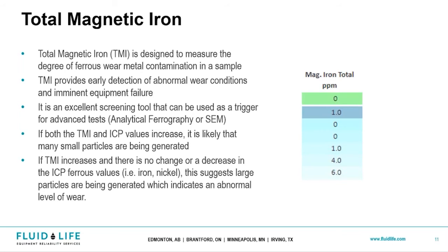And then the other thing that it does is it's going to differentiate things like alloys, whereas an ICP is only going to pick out single elements, right? So you have to do a little bit of consideration and evaluation to be like, oh yeah, there's zinc and there's copper, so I'm looking at brass. This will say, hey, this is brass, right? So it's a little bit more unique, and then it can tell you about different metallurgy, different types of steel. There's different classes, of course. So just something to keep in mind as well.